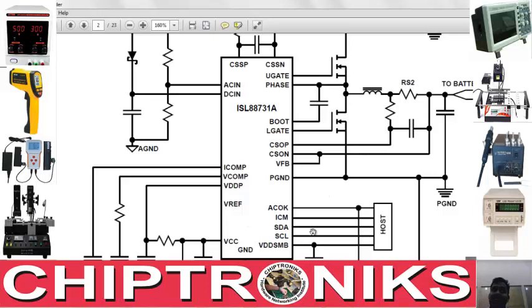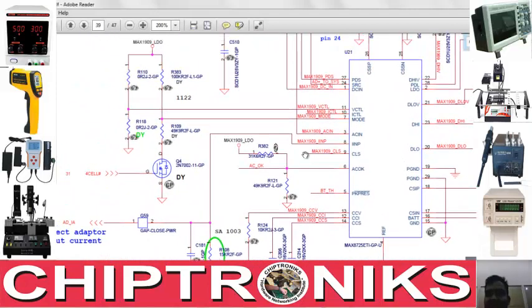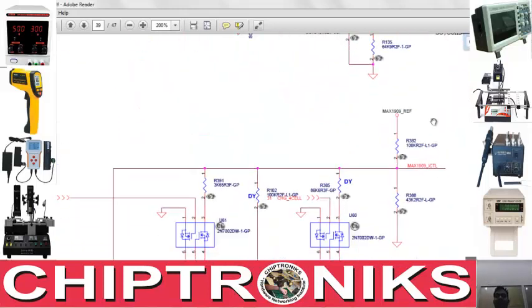So what was ICTL? That was the input limit for the output current. So now how is the IO controller giving that value? The IO controller is giving that value through SDA and SCL, because this ISL 88731 is very smart, smarter than Maxim 8725. Inside this charger IC there are two registers, a charge current register and a charge voltage register, and it gets its values from the IO controller. So it is done through communication. It's not hardwired. Whereas in DV2000 you can see this is ICTL, Max 1909 ICTL, hardwired with charger on functionality from IO.